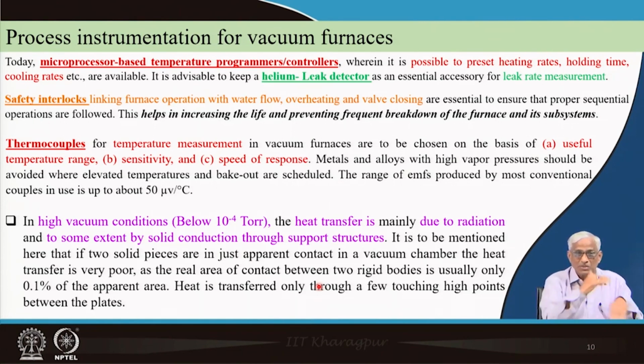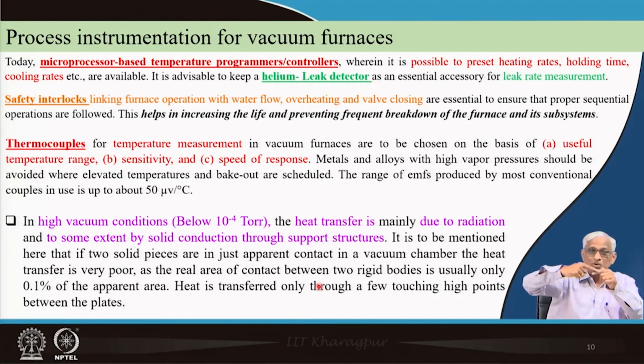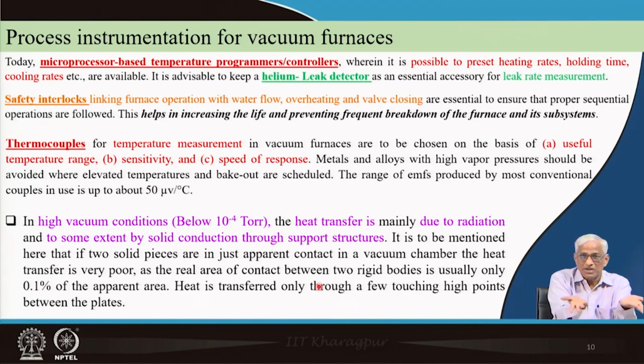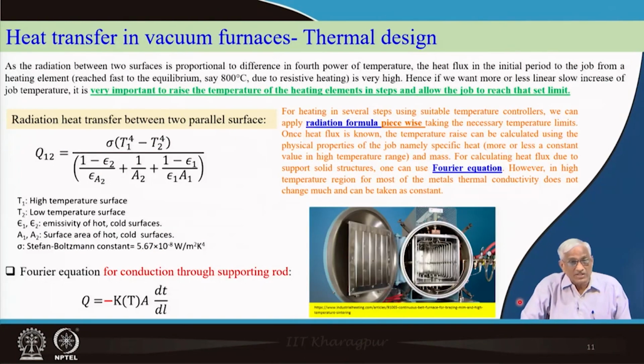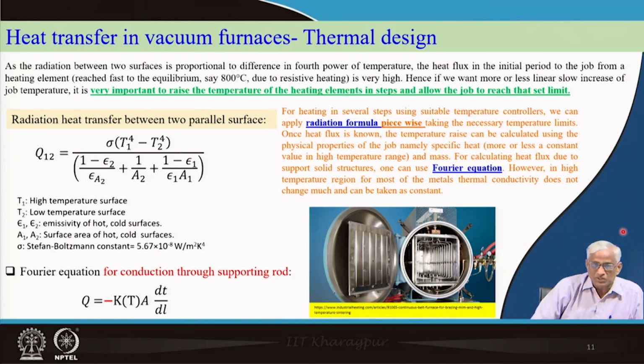That is the problem. Substrate heaters in the semiconductor industry, sometimes we think the substrate heater, if you keep a thermocouple, is showing 400 degrees, but actually the silicon may be at a lower temperature. You have to keep track of that. So, you have to tighten here and there, so that through those conduction rods the front end is also heated. These things we will see in semiconductors when we come to thin film manufacturing again. Okay. So, the sensitivity of the thermocouple has to be chosen.